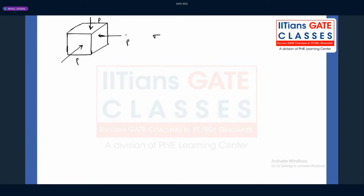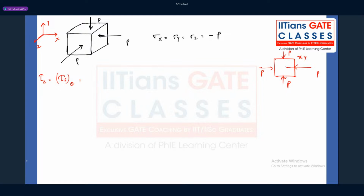That means if you say this particular axis is sigma x is minus p, guys. This is the hydrostatic state of stress condition, right guys? Now, what they're saying, a body subjected to hydrostatic pressure has no shear stress. Now, what is the tau theta? Suppose you are writing for plane stress, I'm finding this tau about the z axis. So I'm considering this is x, this is y, and this is z. Now, guys, understand this is the p value, and this is nothing but the xy plane. In the xy plane, what is my consideration here? I'm calculating the tau about the z axis. Tau theta. I'm taking a plane at an angle theta, and I need to find on that plane what my shear stress is.